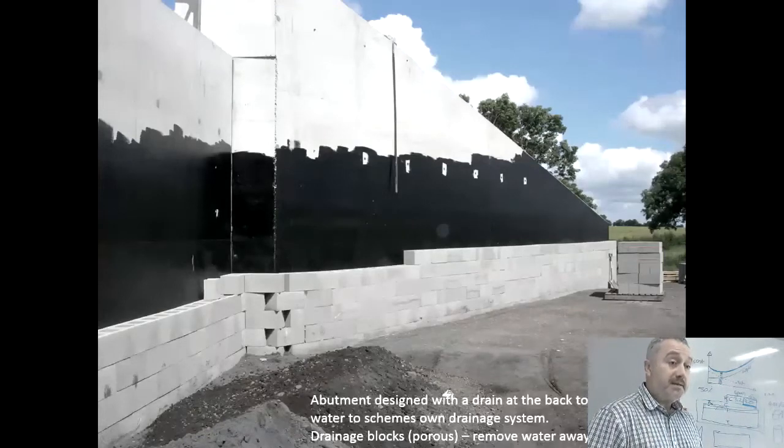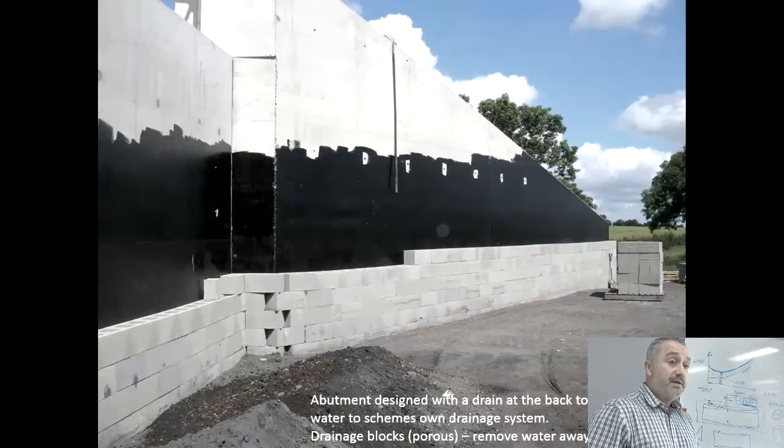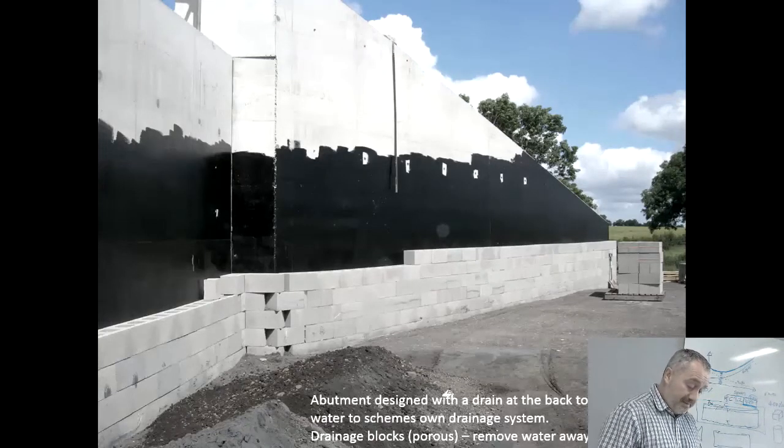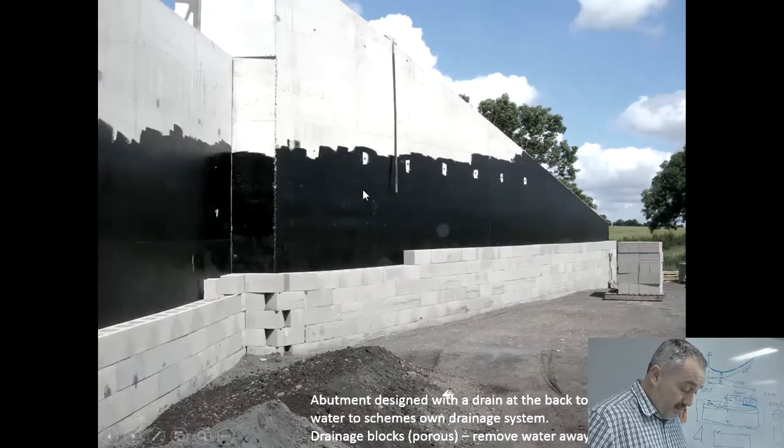The black is a bitumen paint, again to stop the water from going into the concrete. You'll find that all of the chlorides and all the salts and all the stuff that we do to stop frost, all those chemicals impact upon concrete and steel. It's very bad, very bad. But yeah, you've got about two coats of bitumastic paint.